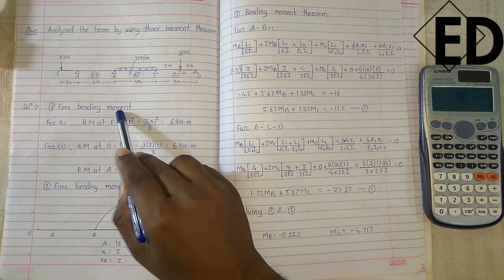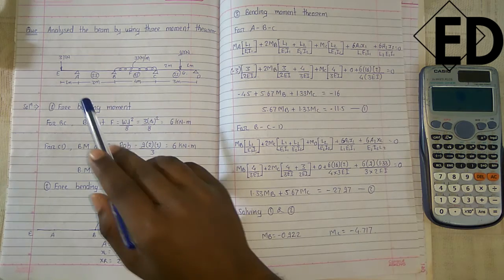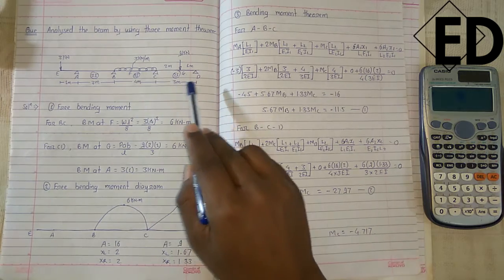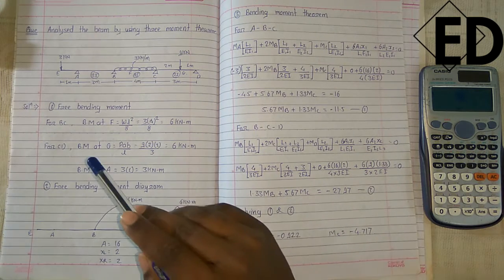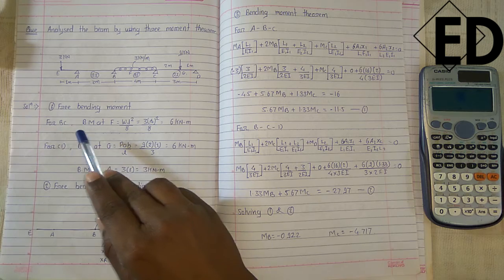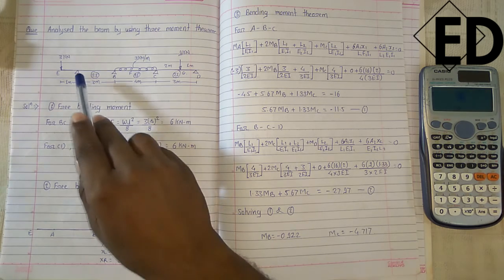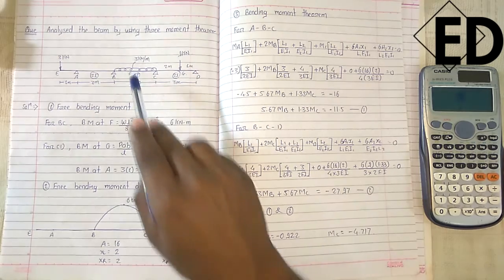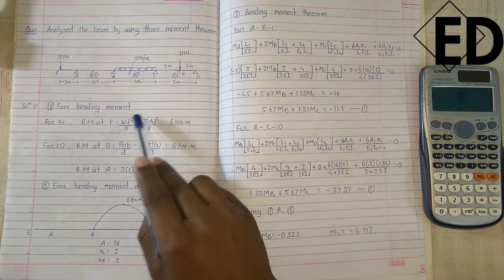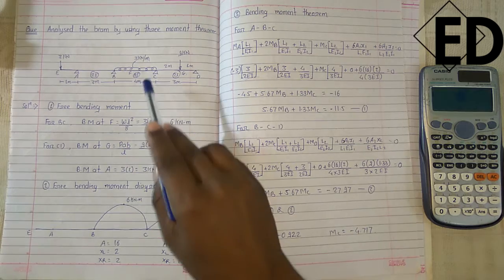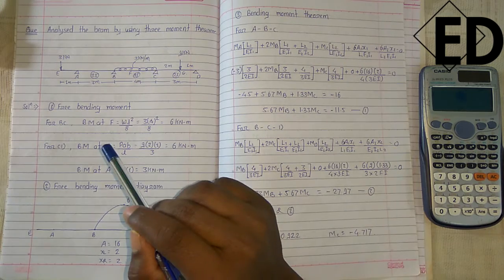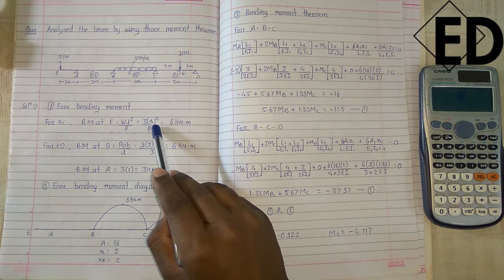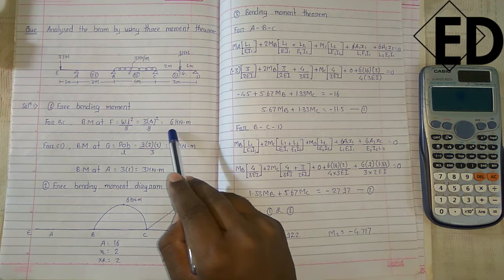Free bending moment is calculated for each span, for span AB, for span BC and for span CD. Let's solve. For span BC, the bending moment at F equals WL square by 8. This is the bending moment for UDL. So by putting all the values, that is 3 into 4 square by 8, we get 6 kilonewton